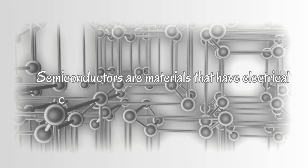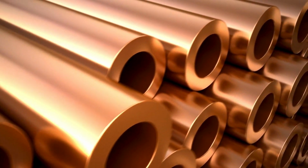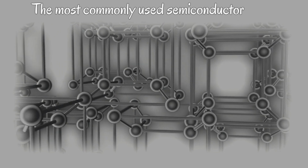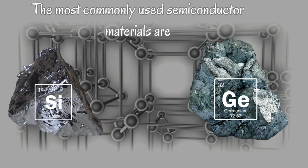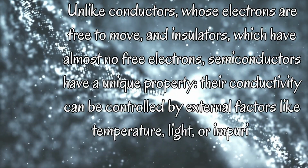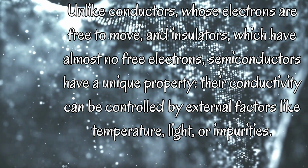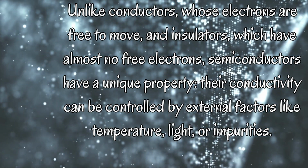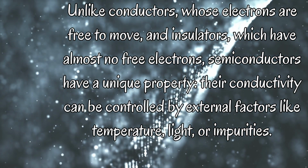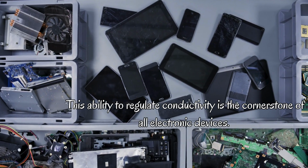Semiconductors are materials that have electrical conductivity between that of conductors, like copper, and insulators, like glass. The most commonly used semiconductor materials are silicon and germanium. Unlike conductors, whose electrons are free to move, and insulators, which have almost no free electrons, semiconductors have a unique property. Their conductivity can be controlled by external factors like temperature, light, or impurities. This ability to regulate conductivity is the cornerstone of all electronic devices.